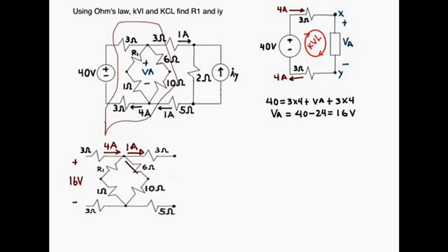And so we write that the first one, I sub B, will be equal to 16 volts divided by 16 ohms, 10 plus 6, that's equal to 1 amp. So 1 amp is flowing through one of the branches of the resistors in the middle.